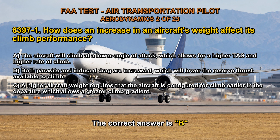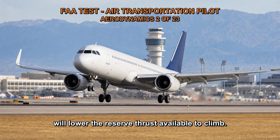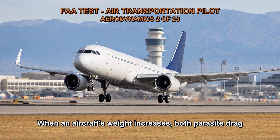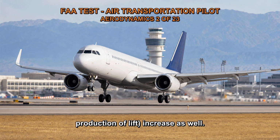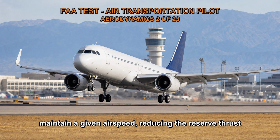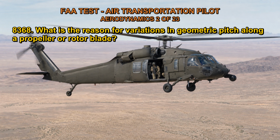The correct answer is B. Both parasite and induced drag are increased, which will lower the reserve thrust available to climb. When an aircraft's weight increases, both parasite drag, related to the aircraft's shape, surface area, and skin friction, and induced drag, related to the production of lift, increase as well. This increase in drag requires more thrust to maintain a given airspeed, reducing the reserve thrust available for climbing. As a result, the climb performance of the aircraft is affected negatively.